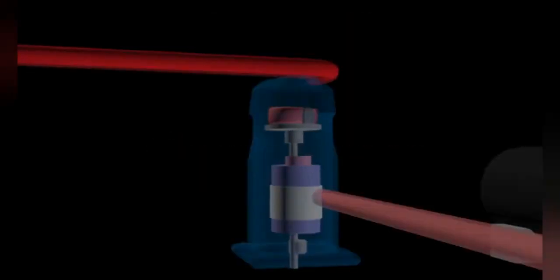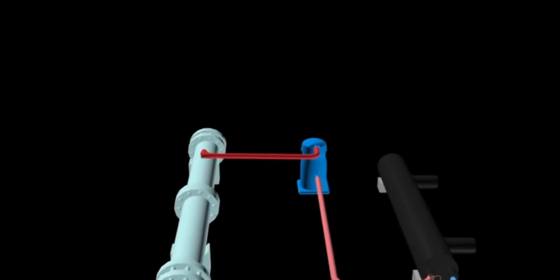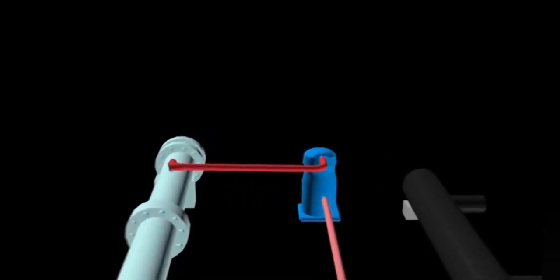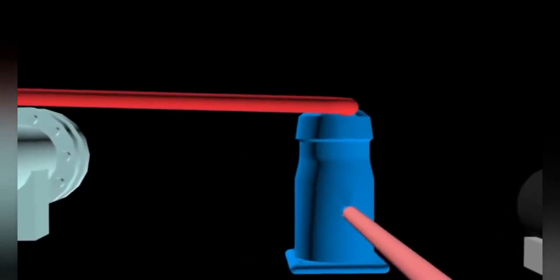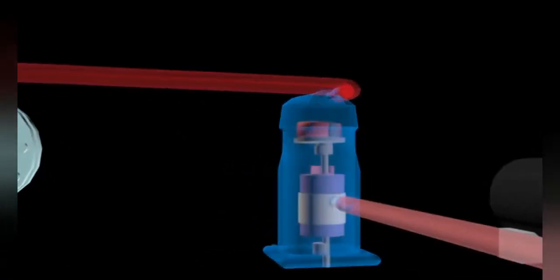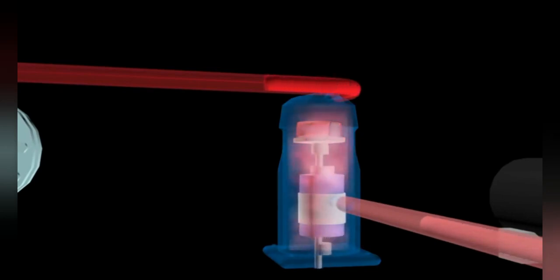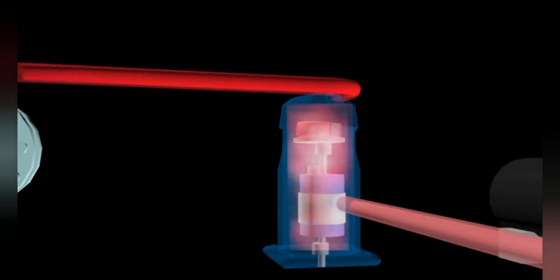Compressor. The compressor works to increase the pressure of the refrigerant. In addition, it also serves to increase the temperature of the refrigerant higher than the temperature of the condenser water so that the heat transfer can occur in the condenser. The refrigerant enters the compressor as a low pressure gas and exits as a high pressure gas.